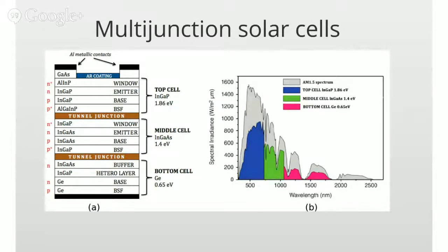In other words, the green photons will not be absorbed by the indium gallium phosphide, the highest energy cell. That would be a non-absorption loss for the top cell. But now by putting another cell which will absorb that, you can avoid that loss. And the same thing with thermalization. These blue photons, which have very high energy, if you try to absorb them with germanium, you will have thermalization losses. They will have very large energy and they will lose heat, because it's a small band gap. You can avoid that by just grabbing it in a different cell.